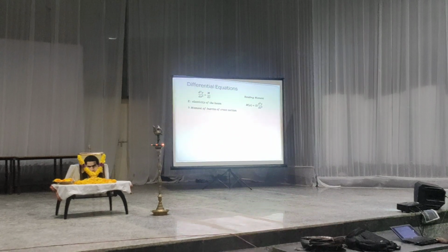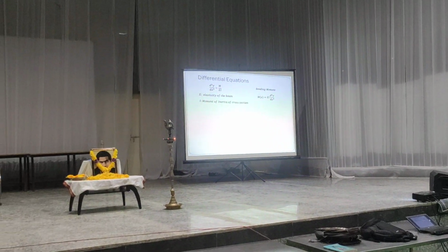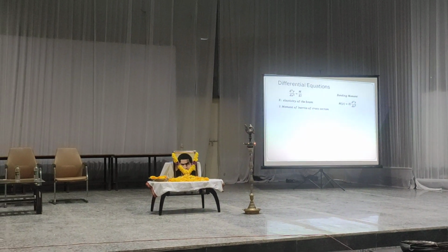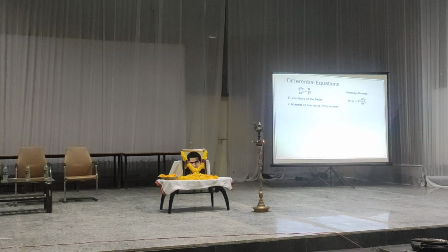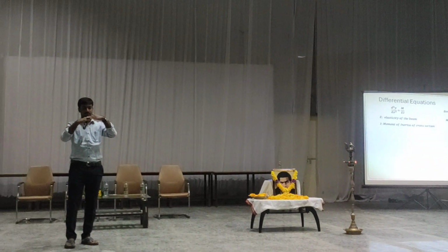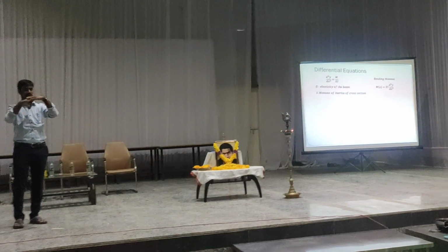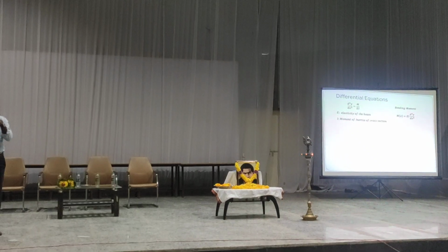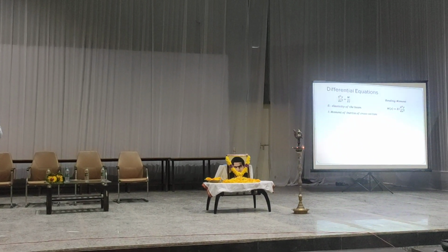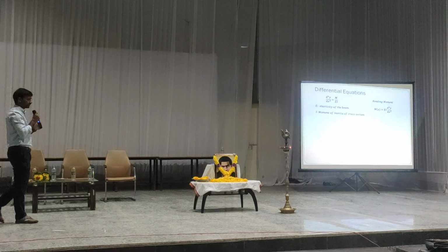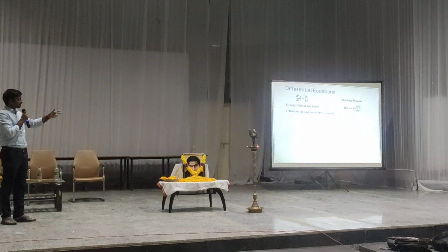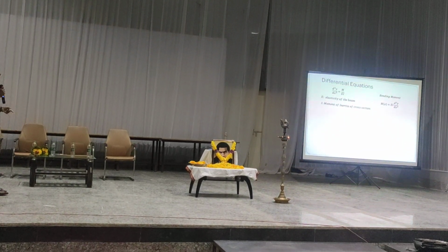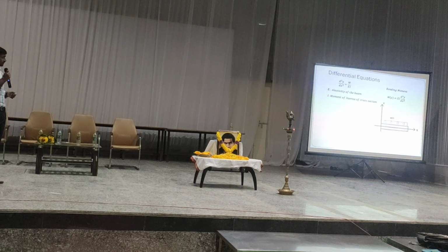And if you want to know the shear force, what is shear force? When you bend a beam, there will be two forces which are going to act. One is a horizontal one, and another one is a vertical force. Or when you slide two plates, there is going to be some force which is going to occur. So when you bend it, there will be a vertical force which is going to act on it, and that force we are going to call a shear force. To calculate shear force, you can differentiate that bending moment, and that will give you shear force. And if you differentiate one more time, that will give you the deflection, not the deflection.